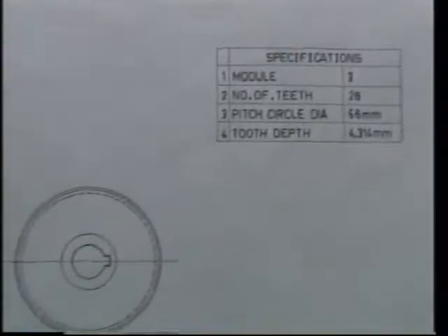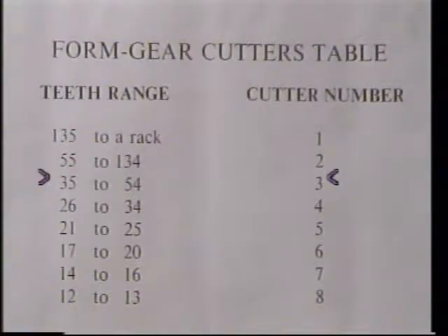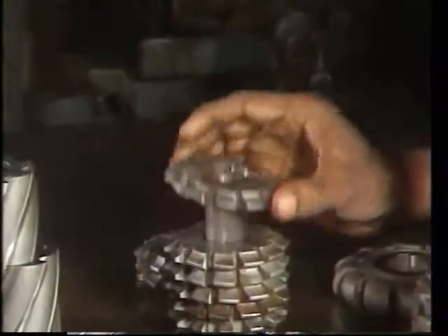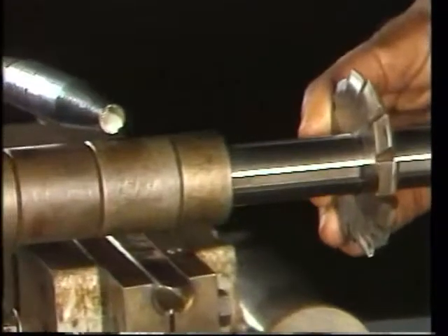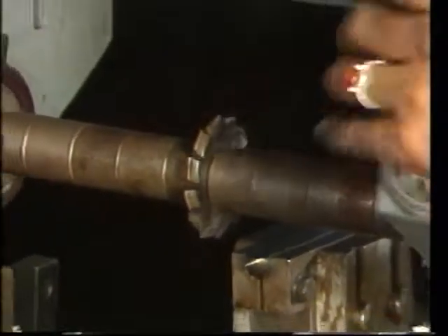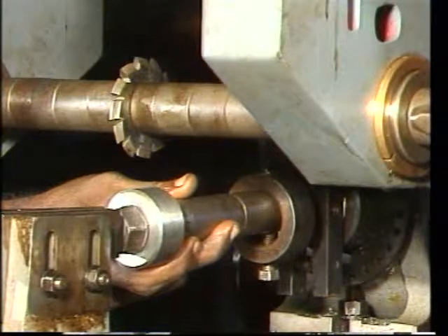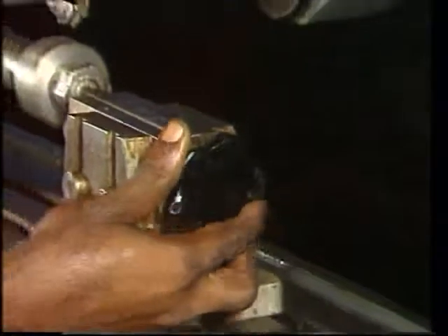The working gear drawing provides all the necessary data for gear forming on a milling machine. The cutter selected for the given condition is number 4 of 2 mm module, which will produce the required involute tooth form for 28 teeth. The selected cutter is mounted on the arbor of the milling machine. In order to fit squarely on the fixture, the blank diameter, the bore, and the working faces are machined true to each other.